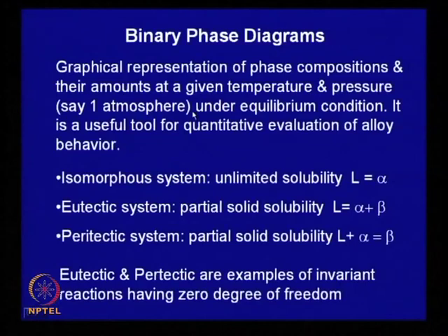One important condition here is we assume that the cooling is very slow, such that at every stage there exists an equilibrium between liquid and solid. These binary diagrams are a very useful tool for quantitative evaluation of the microstructure of the alloy, and hence we can also infer something about its mechanical and other physical behavior.